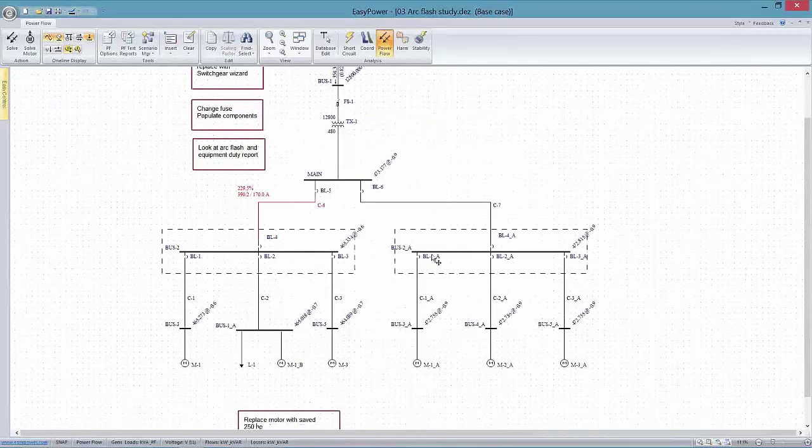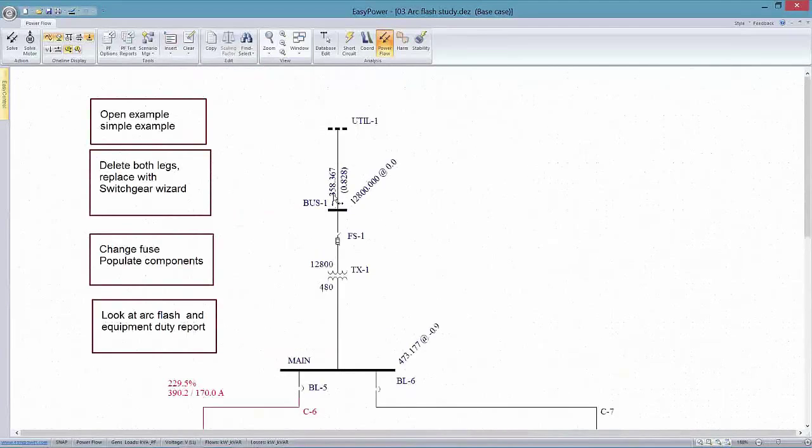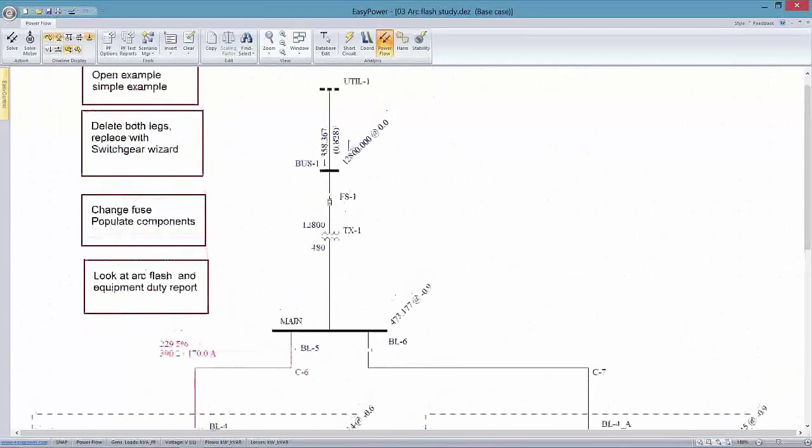Because we have virtually all motors as loads, what we see here is that we're drawing 358 kilowatts from the utility at a power factor of 0.828. In and of itself, this actually could incur significant power factor demand penalties at most utilities in the United States.